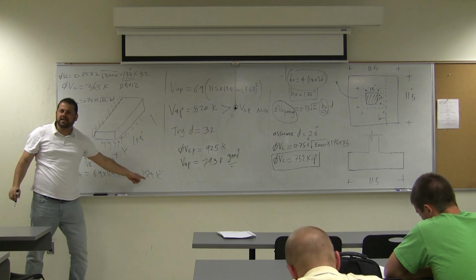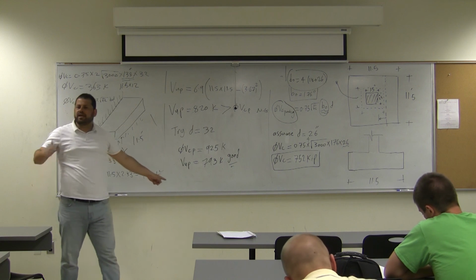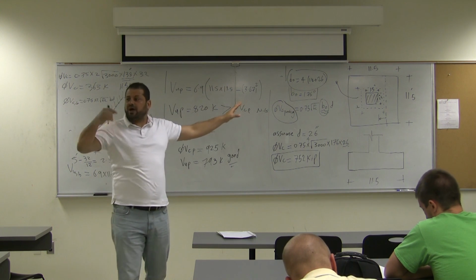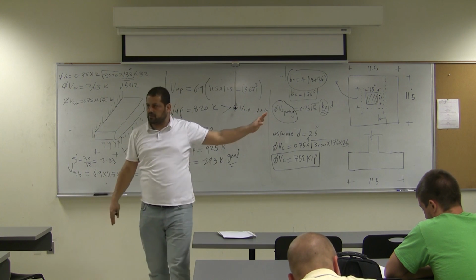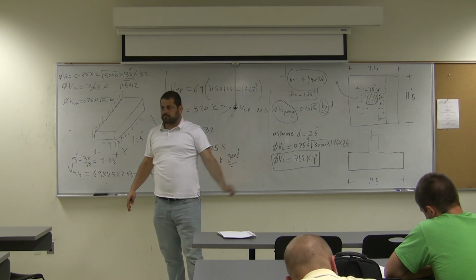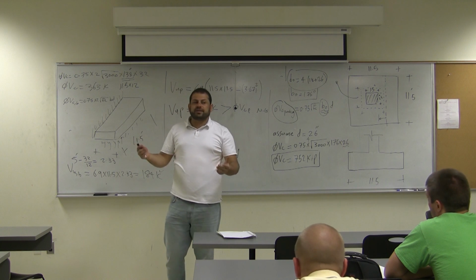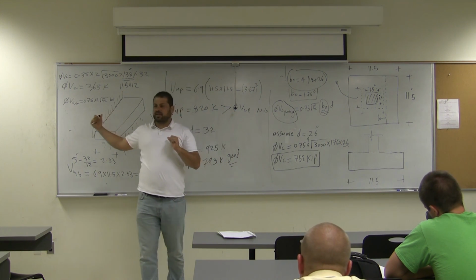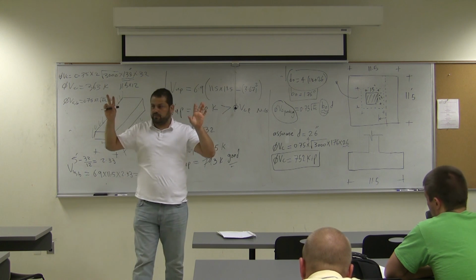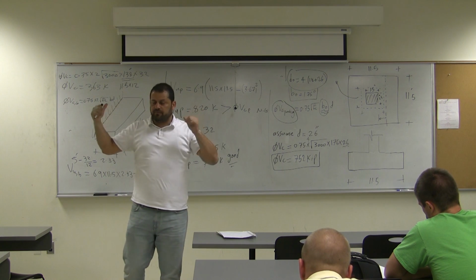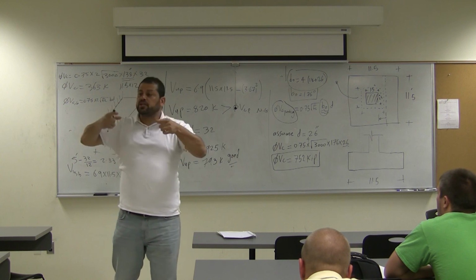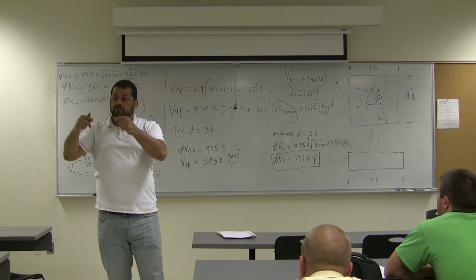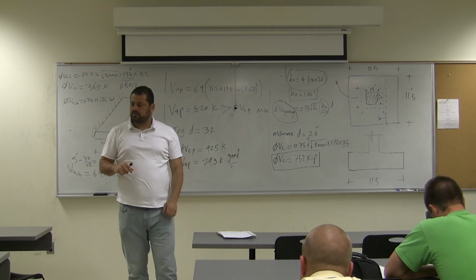I told you, single column footing beam shear is secure because D is determined based on punching. But you have to check it. For some cases, it may not work. You have to check it. Okay? In combined footing, this is what controls the design. The beam shear controls the design. Combined footing, there is more than one column. So you get D from the beam shear. Then under each column, you assume that column by itself will punch. Then you check punching for each column by itself.